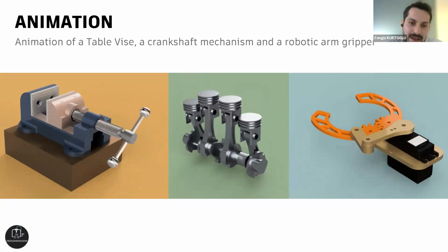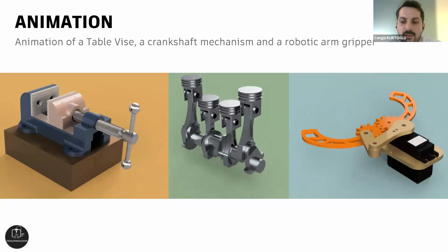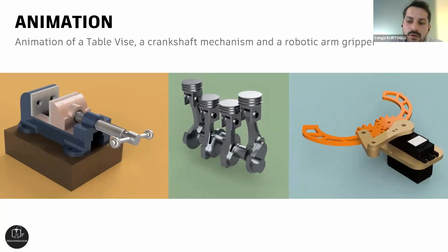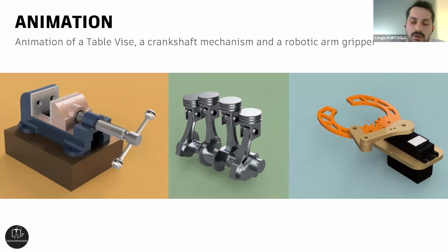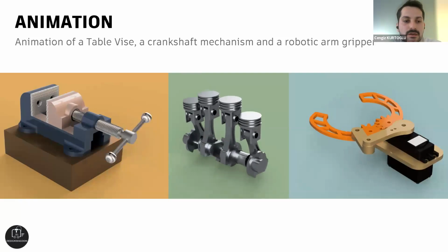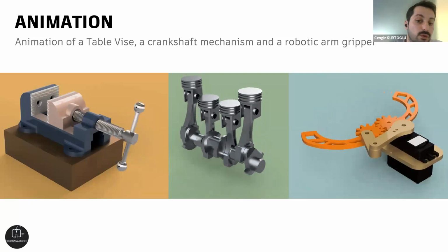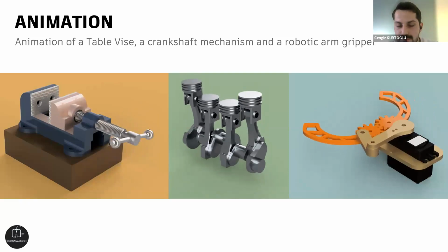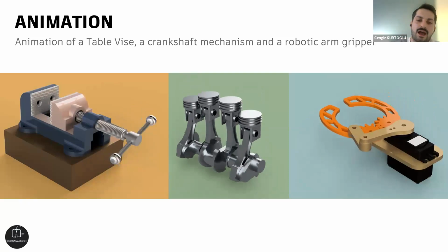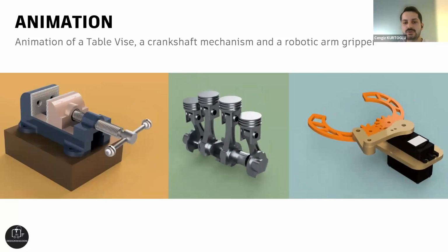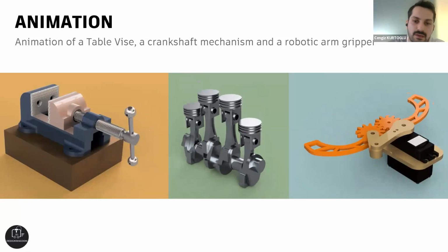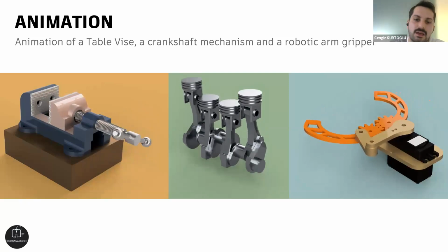Well, in the animation workspace, we can do quick camera animations, or we can use the auto explode tool to create these types of animations. And also, I generally prefer to use a motion study in the design workspace. We will discuss it in the software session.